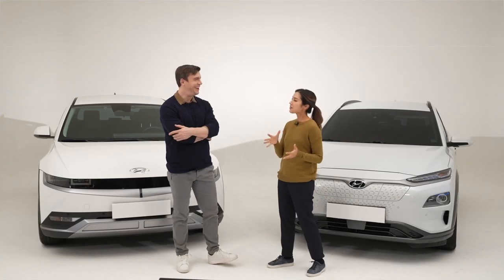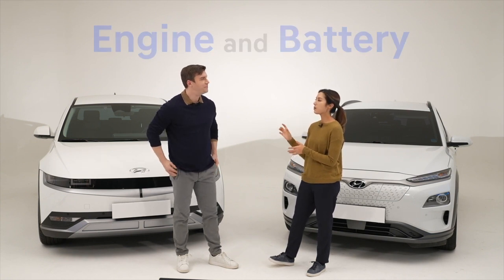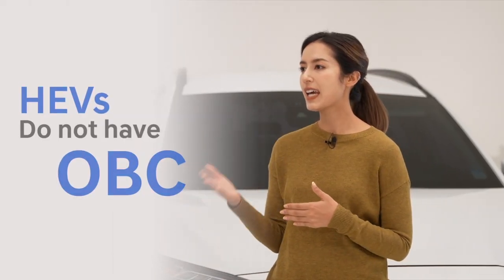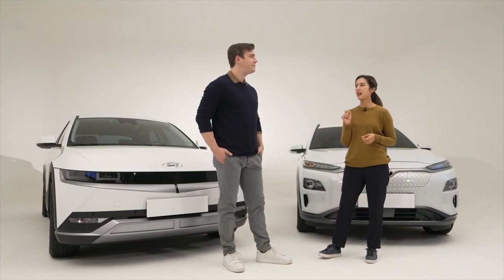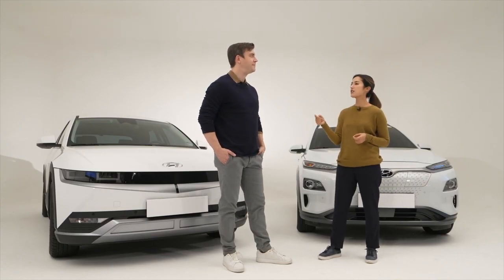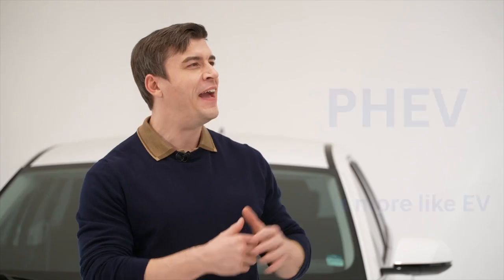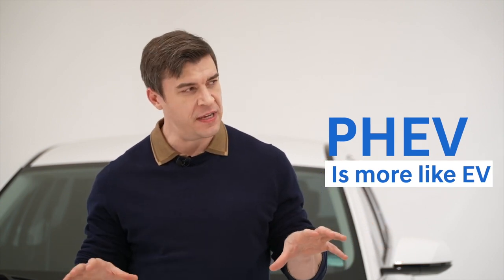But now these HEVs use both engine and battery power. Very good. So both an engine and fuel tank are needed, but as charging isn't necessary, HEVs don't have an OBC. PHEVs, on the other hand, do need charging, so they have an OBC to take care of that, right? Very good. They have more characteristics of EVs than HEVs.